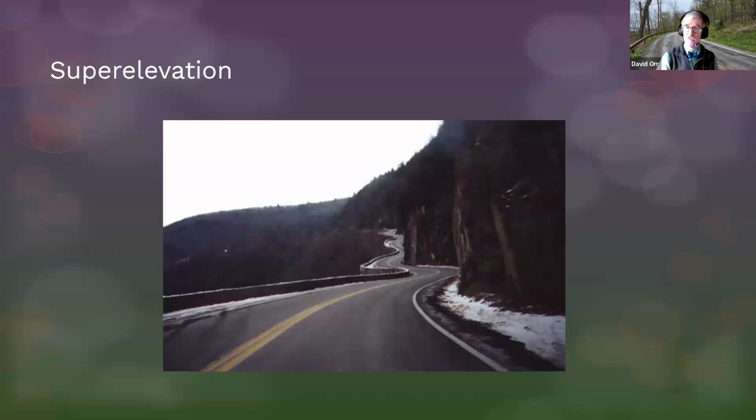And of course, super elevation is a big issue. If we had a whole day, we could spend a good bit of time talking about super elevation and how much super you need given the speed. It helps us by essentially helping us with the friction values on the roadway, and we can get around the corner faster. So we've got a good super elevation on this roadway here. It makes it safer for a lot of reasons, but we can't go too steep because of snow and ice control, and we do have to worry about the overbreak at the shoulder.